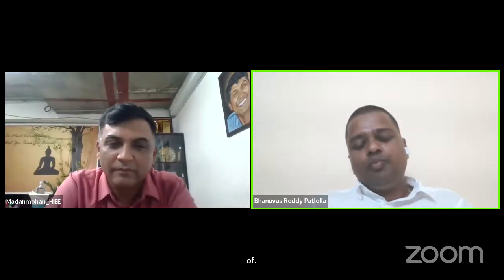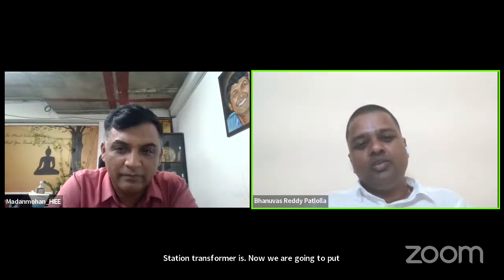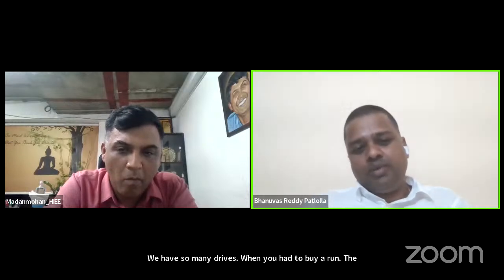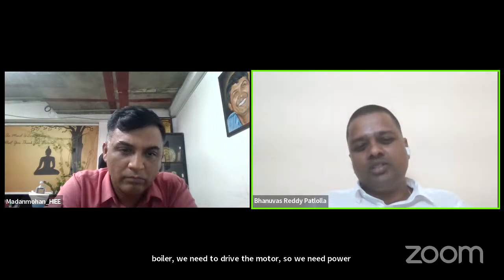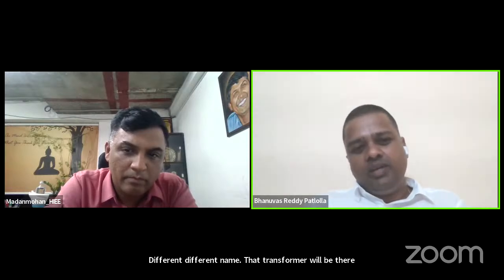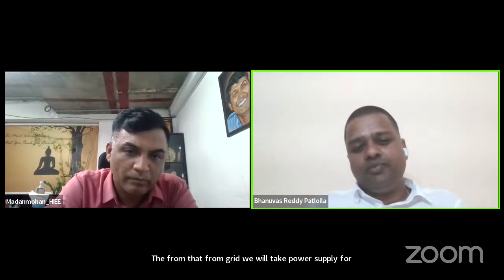So there is no power for commissioning the power plant. We have so many drives. We need to run the boiler. We need to drive the motors. So we need power supply, a reliable power supply. The station transformer, you can say standby transformer, people use different names. From the grid we will take power supply for the transformer, and that will be fed to our HT switchgear. Further distribution will be there.